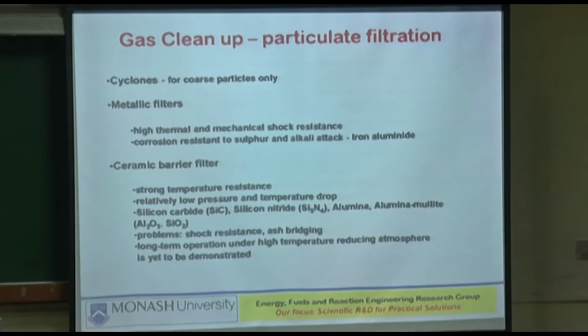Now the question is, what is a coarse particle? What's the cutoff? Maybe 10 micron? Anything below that, cyclones will not be that effective. They will pass through.